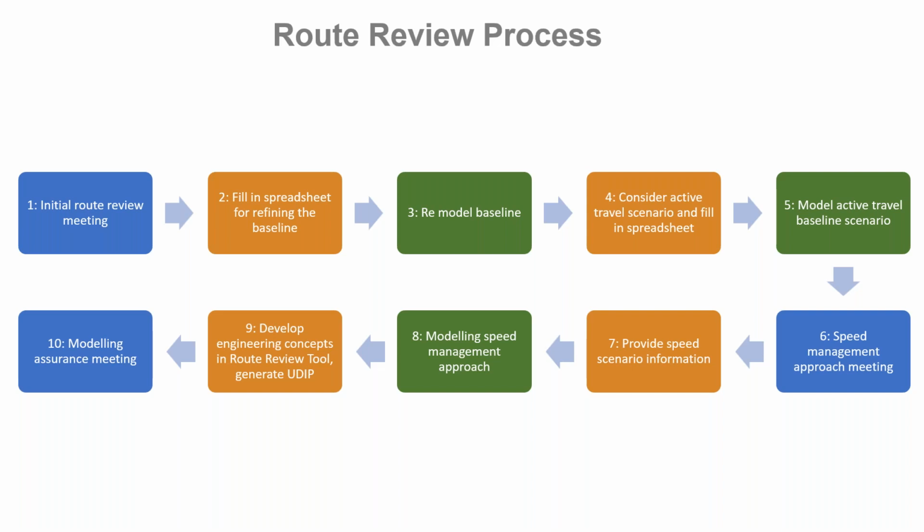It might be a speed limit change paired with some enforcement technology, or it might be a speed limit change paired with some road infrastructure improvements. And what we do then is have a look at all of the proposed speed management strategies and what the likely impact on 85th percentile and mean speeds is likely to be, so that we can model the impact of those treatments. Just to give you an idea, what we're doing is basing that on logic.